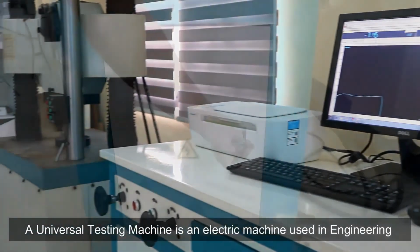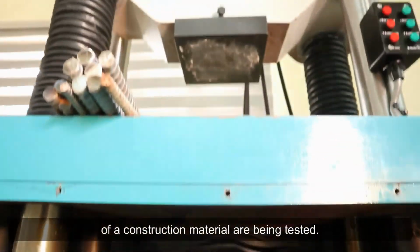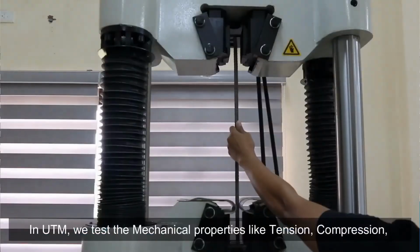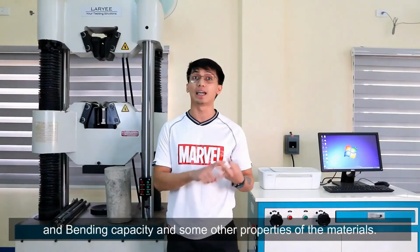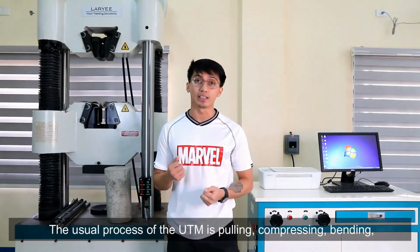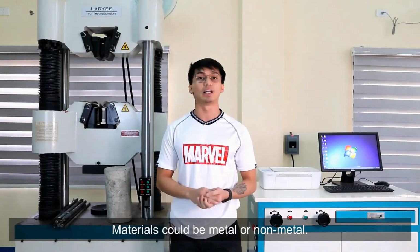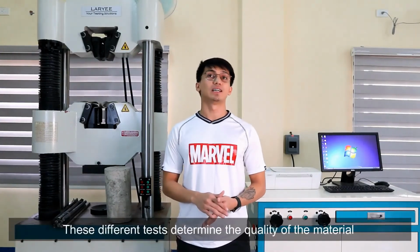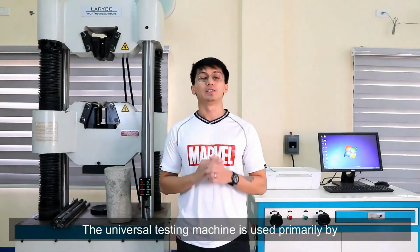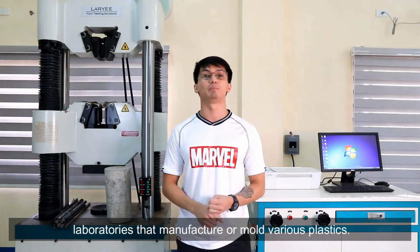A universal testing machine is an electric machine used in engineering where the main mechanical properties of a given specimen of a construction material are being tested. In UTM, we test the mechanical properties like tension, compression, and bending capacity, and some other properties of the materials. The usual process of the UTM is pulling, compressing, bending, or stretching materials until they break. So materials could be metal or non-metal. These different tests determine the quality of the material as well as how suitable it is for a particular use. The universal testing machine is used primarily by laboratories that manufacture or mold various plastics.